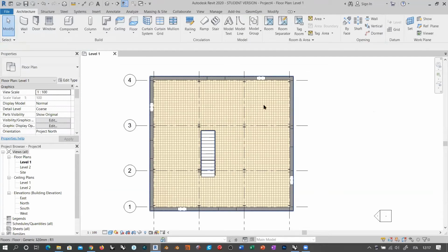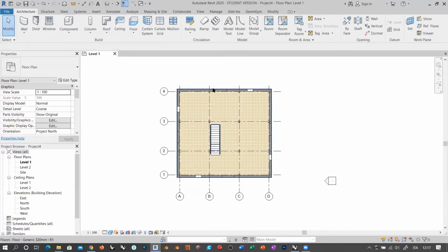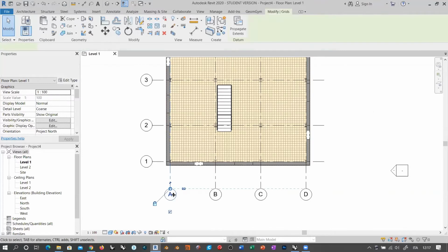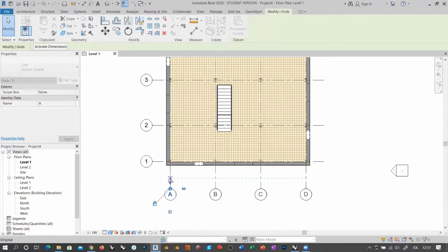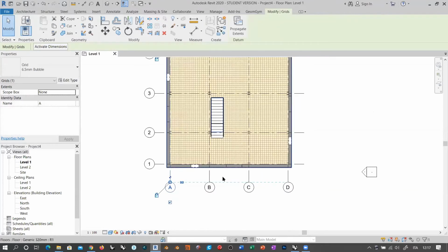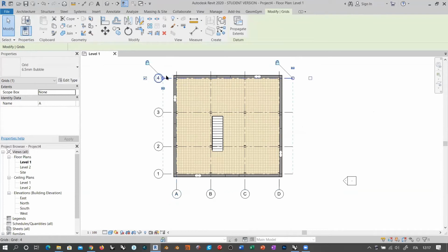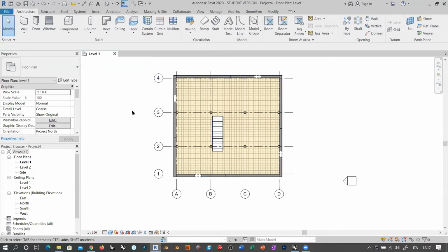This belongs to the property of the material, which is properly recognized by Revit. So yeah, everything is working properly. You see the grid axis. You see that they are already connected together as regards the extension because they are basically the same length from Grasshopper. So both the directions for these grid lines are already connected.